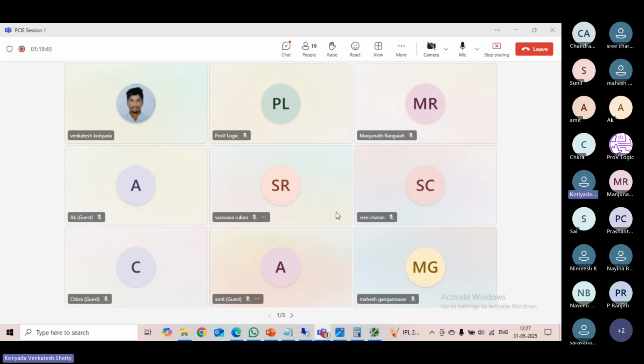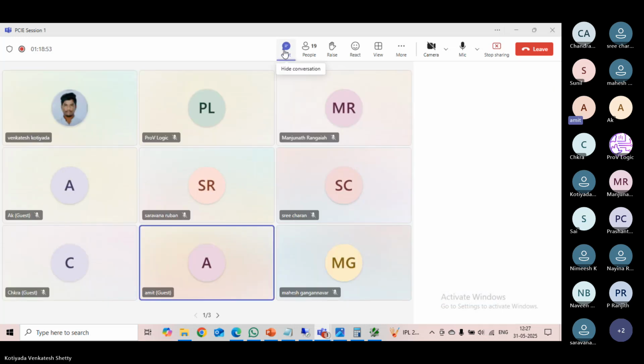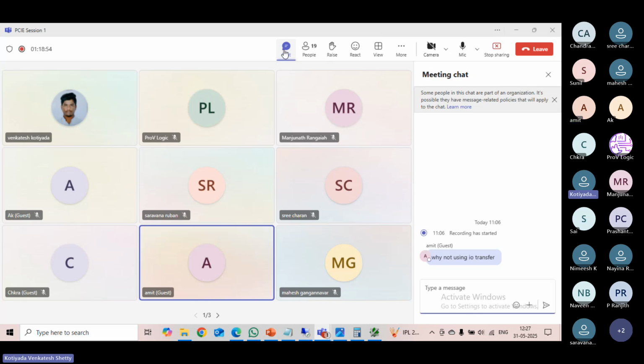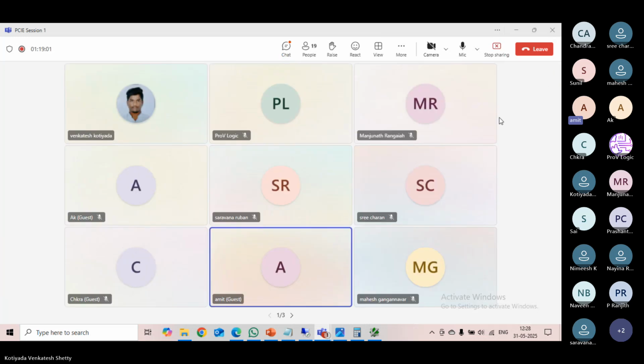For the DL tracker, the data link layer tracker, you can check the ACK/NAK protocol flow. DLL packets we can check in the DL tracker. The flow will be similar to the physical tracker you shared on screen: half the part from the transmitter, half from the receiver. Both will print at the same time, meaning sender and receiver.